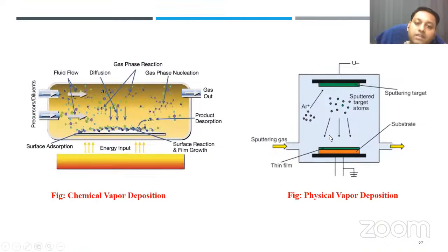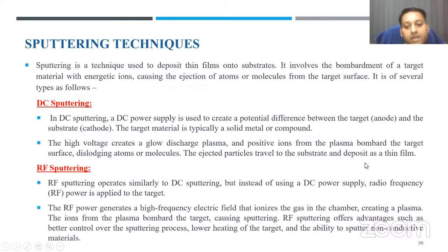Okay, so in this case only we can achieve metal deposition on the substrate. In the case of insulating material deposition, you require a very high electric field. Then DC sputtering is not at all applicable. We need to apply a very high potential. So instead of applying a very high potential, we apply an RF field across it, which can break down the target, and then gives rise to the bombardment.